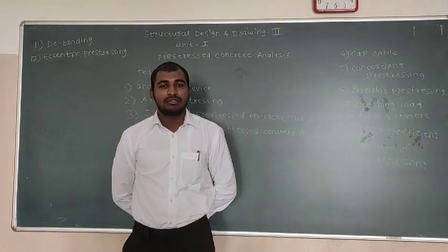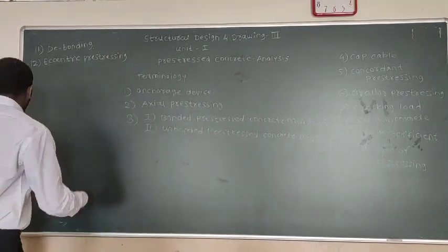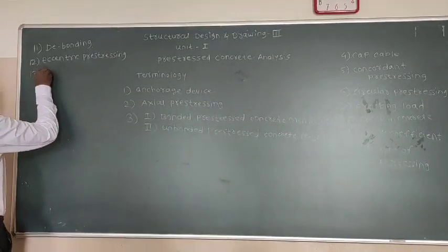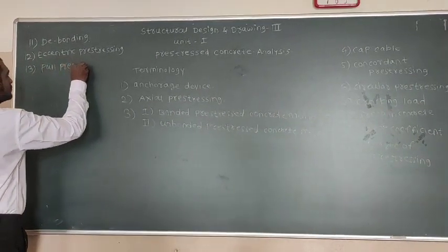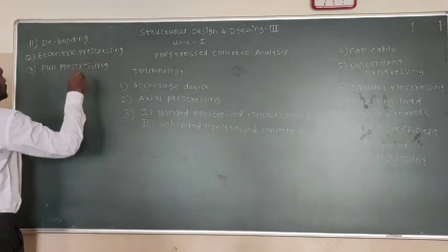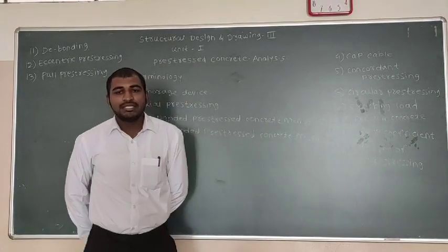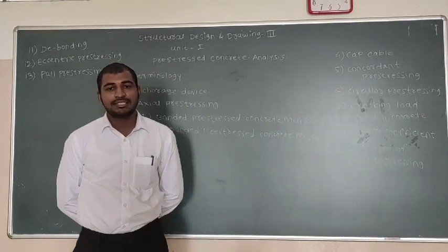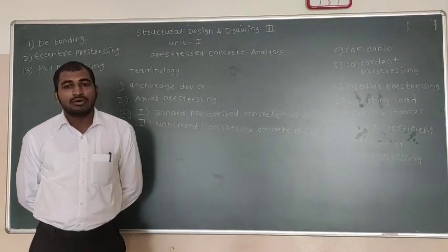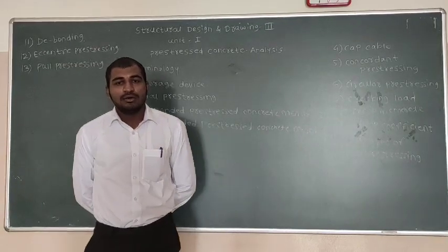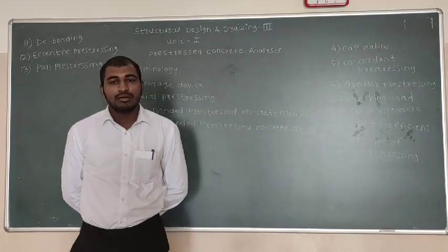Then the 13th terminology is full prestressing. Full prestressing is prestressed concrete in which tensile stresses in the concrete are entirely obviated by having sufficiently high prestress in the members.